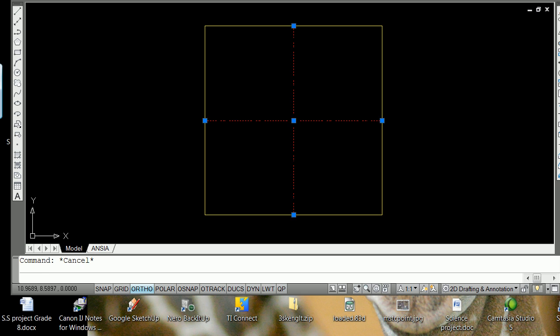You now have your center lines drafted, but unfortunately those center lines, if you click on them, go all the way through. If you do not have your snaps on, it is quite easy to go BR for break, or right click break, select very approximately, break again, select very approximate, get close, and now you can go F for fillet. The radius is set to 0. You click on the two things you want to keep. You can do that again here.